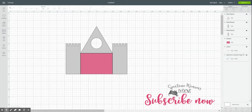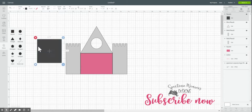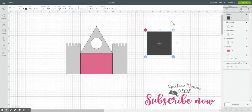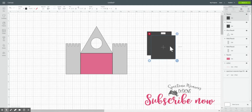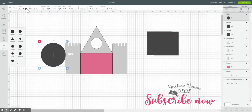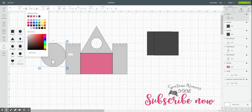Okay, now before we go any further, I want to show you something, okay? Oftentimes I'll see people say, oh, my slice button, it's not lit up, it's not working. Almost 100% of the time, the reason is that you have more than two items selected to slice. Your slice button will only work if you have two items. So I'll show you here.